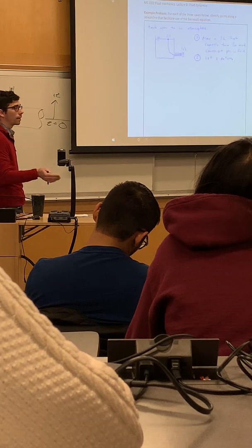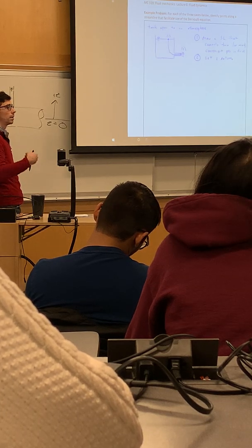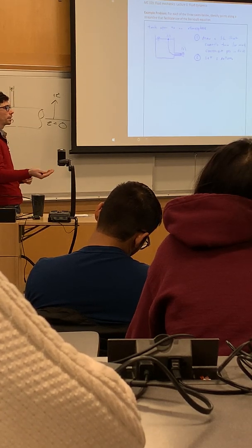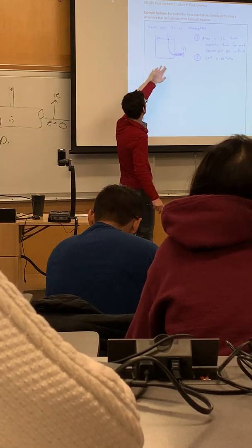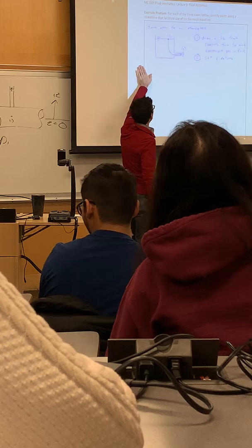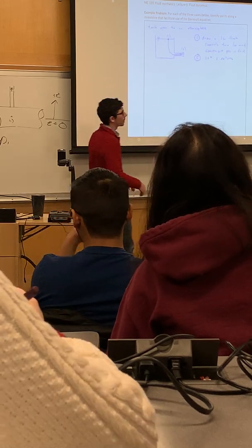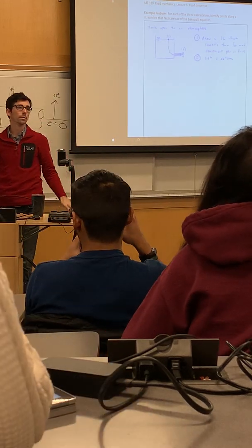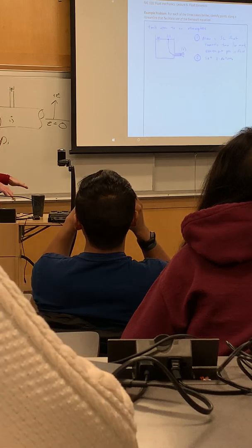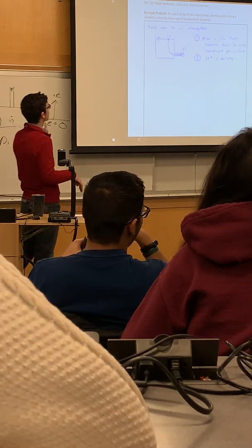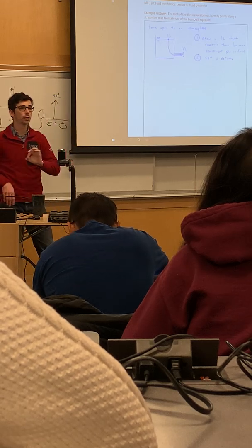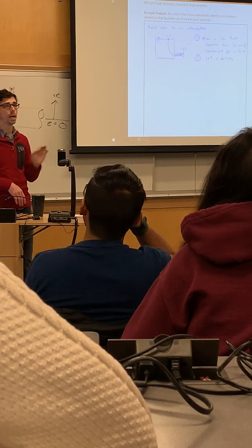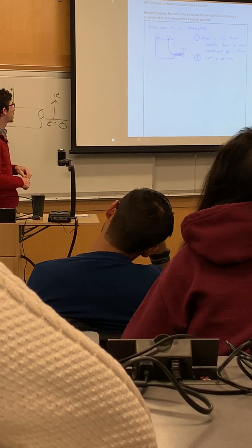Recall that in all of our derivations that led up to this, we talk about how pressure increases with depth, or at least for our hydrostatic pressure derivation, we made that derivation with the datum lower in the fluid. You can solve these problems with the datum at the surface of the fluid. It just starts to get a little bit tricky to track your negative signs that they created in that example.